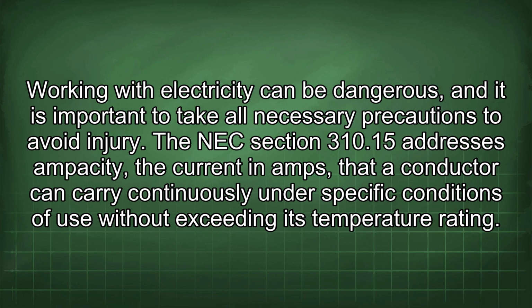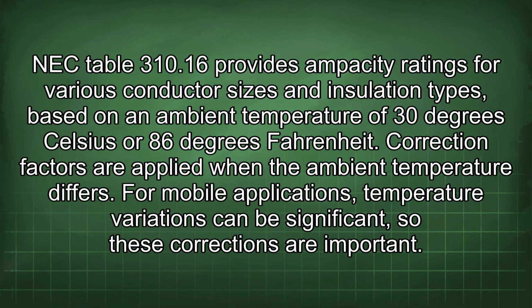The NEC Section 310.13 addresses ampacity, the current in amps that a conductor can carry continuously under specific conditions of use without exceeding its temperature rating. NEC Table 310.16 provides ampacity ratings for various conductor sizes and insulation types, based on an ambient temperature of 30 degrees Celsius or 86 degrees Fahrenheit. Correction factors are applied when the ambient temperature differs. For mobile applications, temperature variations can be significant, so these corrections are important.